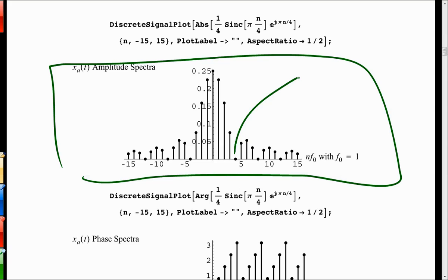Yeah, there's a 0 right there at 4. So what does that tell you? The sinc function has its nulls at multiples of 1 over the pulse width. Now, except that 0, from L'Hopital's rule, it has 1 there. So that is 1 over tau, right? 1 over the pulse width.